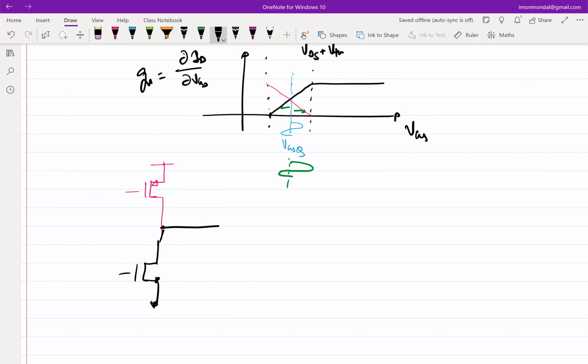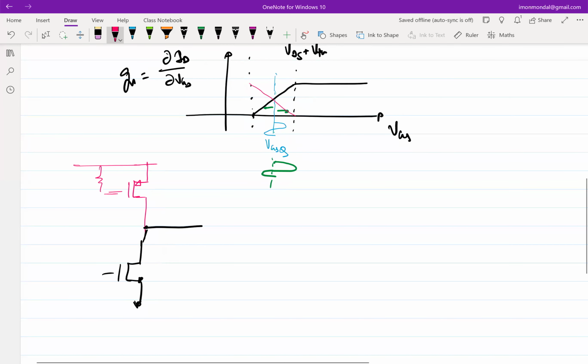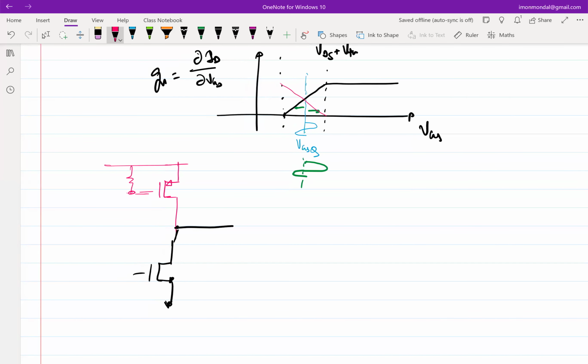So you'll have to ensure that these devices are biased with however your favorite biasing scheme. And then you can apply the input here maybe. You can bias it through a current mirror, you can bias it with a resistor divider. Each of them has its own pros and cons, and I assume you know this from your experiences in analog circuits.